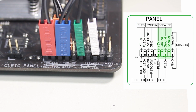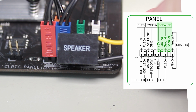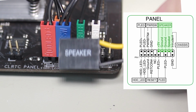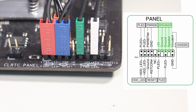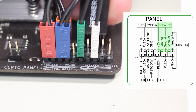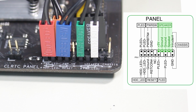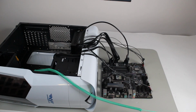The last connector that I will attach is the PC speaker. This used to be part of the computer case, but nowadays you will generally find the PC speaker is a small speaker that is attached directly to the motherboard. The PC speaker will generally have a black wire, which is a negative wire. The positive wire will be generally red or yellow. Make sure that it is plugged in the correct way, otherwise it may not work. This is the last of the connectors from the computer case that need to be plugged into the motherboard.